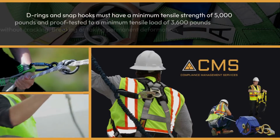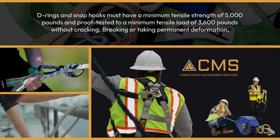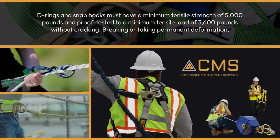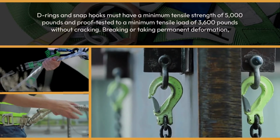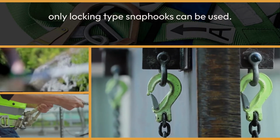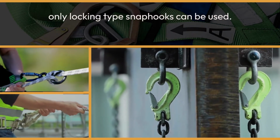D-rings and snap hooks must have a minimum tensile strength of 5,000 pounds and proof tested to a minimum tensile load of 3,600 pounds without cracking, breaking or taking permanent deformation. Only locking-type snap hooks can be used.